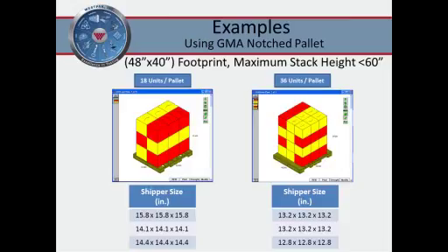And next here we have a slide that just shows there's plenty of palletization software out there. For this example, we just use TOPS, and it's kind of like plug and chug. You take your numbers and stick them in there, and you have a pallet and you stick your dimensions in there and also your maximum stack height, and it'll spit out a diagram for you with how many shippers per pallet.